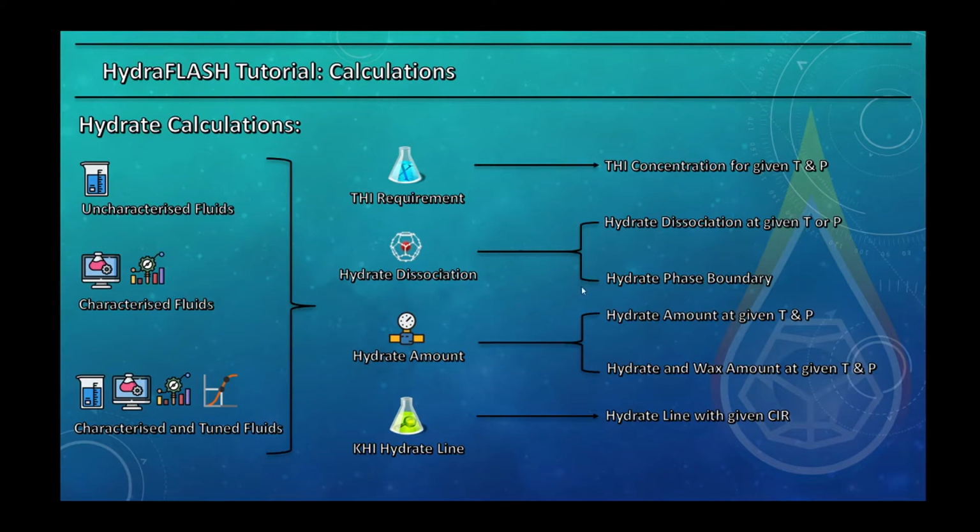Okay. So the next one is the hydrate amount. So for example, you are working under the condition at a temperature or pressure where hydrates are stable. It calculates how much hydrate, how much mass of hydrates you will have in the system at infinite time. And by infinite time, I mean equilibrium condition. Equilibrium conditions happen in an ideal mixing pattern and an infinite time.